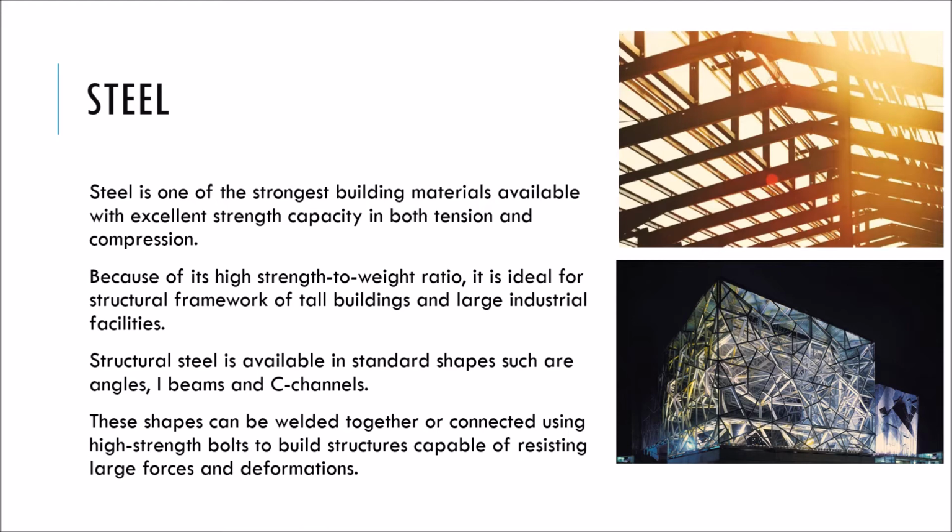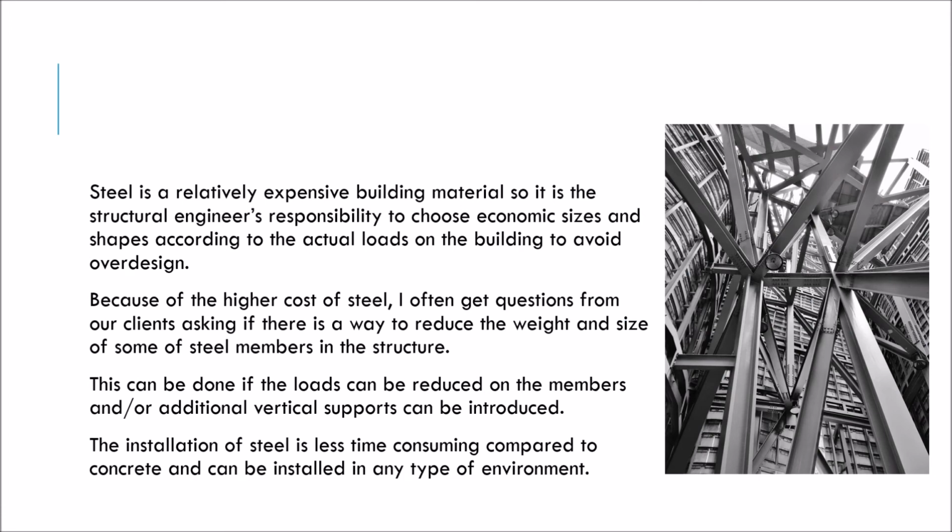These shapes can be welded together or connected using high-strength bolts to build structures capable of resisting large force and deformation. Steel is a relatively expensive building material, so it is the structural engineer's responsibility to choose economic sizes and shapes according to the actual loads on the building to avoid over-design.